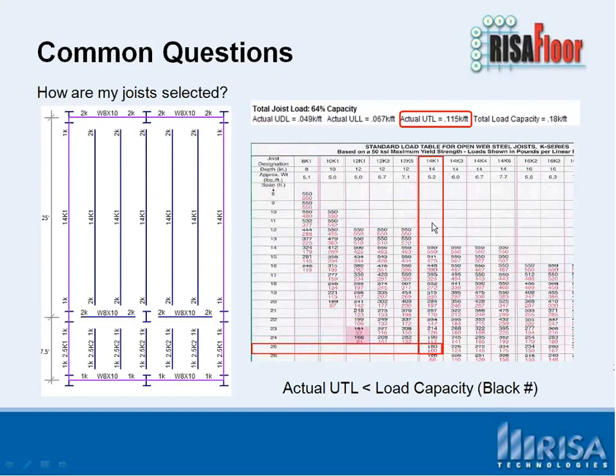What we picked is that 14K1, and that's 180 pounds per running foot as its capacity. You can see from the table that there may be a 12K5 that would work, but there's nothing actually filled in that table there. So we're going to use the next one available, which is the 14K1. Okay, so look through the table and make sure you understand how those are being picked.